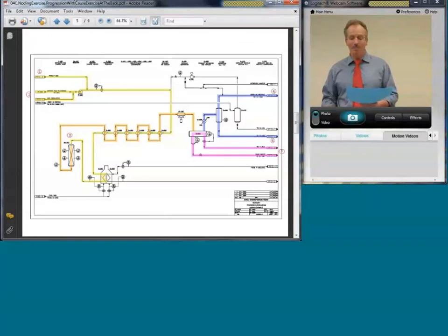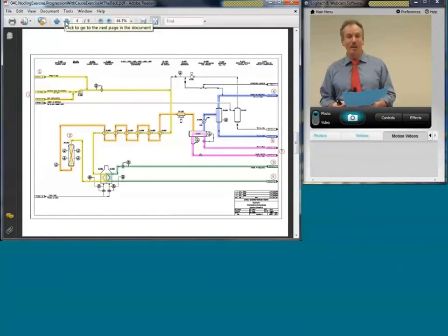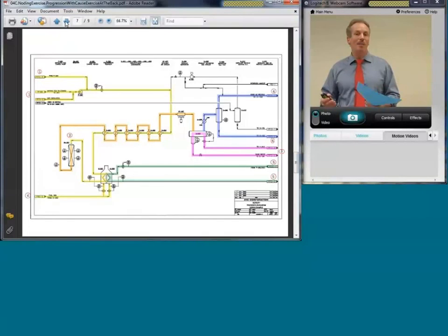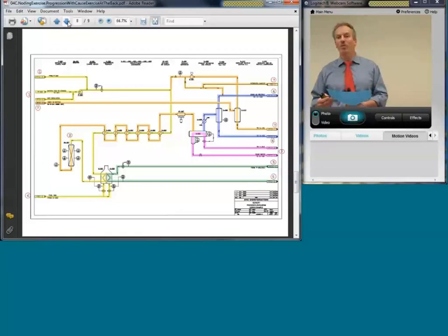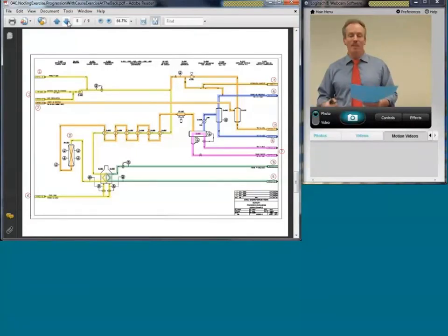And for this type of process, the last piece is basically in the upper right-hand side, which is associated with the suction knockout pot. These are the sort of things that would be picked up last and basically complete this portion of the process. Notice that we've been defining the nodes on the process flow diagram, even though the P&IDs have more information in terms of understanding the process and setting it up so that you've got dynamics that you want to work with the team on. This is very effective.